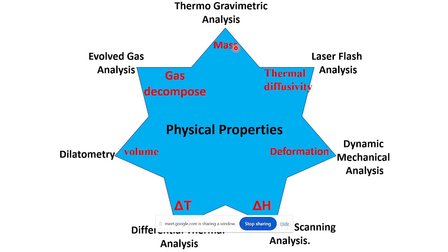For that, you need to take a very small amount of your material. You put the material inside a TGA machine, and there is also a standard material. With respect to that, you are measuring the weight loss. For example, a rubbery material has different components because it is a composite.